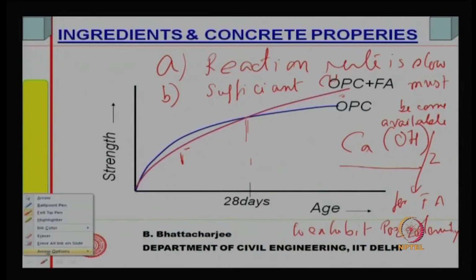Whenever you add pozzolana addition, blended cement, of course, grinding can be more to compensate for this somewhat, but if you add fly ash as part of the mix and design it for the same 28 days strength, early strength is unlikely to be high, and demolding time may be more. This one must keep in mind, but this is not a problem, because you can always design for higher 28 days strength as well. The point is, if you have the same 28 days strength, early strength is usually less when you have a mineral admixture like fly ash added into the system. But what about long term strength?